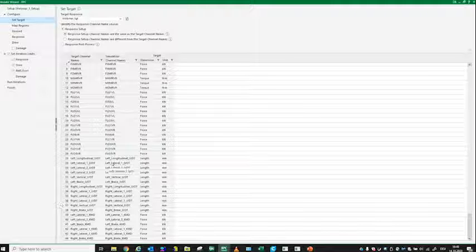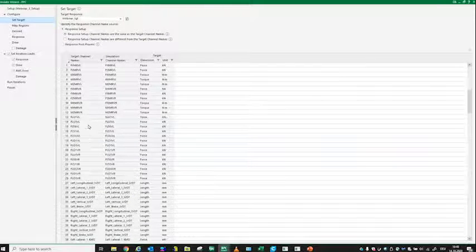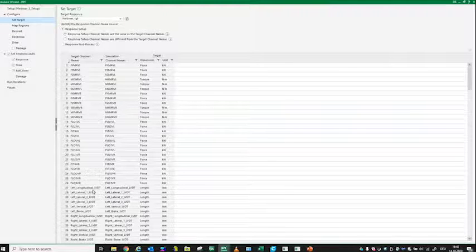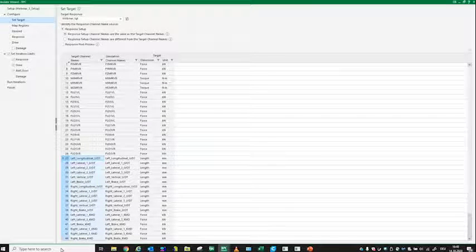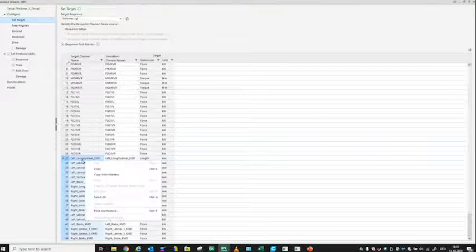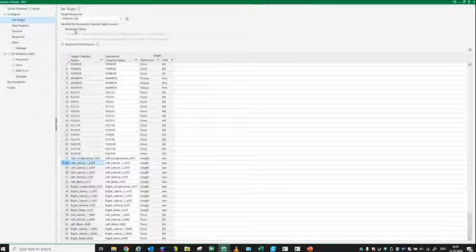Now the question which was previously asked in the seminar is: all channels which are listed up here will be treated as correlation channels. So all channels I show up here will go through the iteration process and be shown as a correlation one, which you are familiar with from Pro. And if I decide my FRF was a 12x12 and I want a 12x26, I do the same thing I did in the model stage. I select the post process, and then I am able to remove channels, remap channels, and whatever I like to do here. So this is the kind of flexibility we have here.